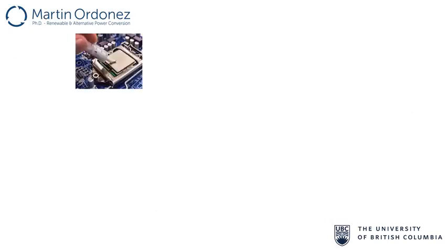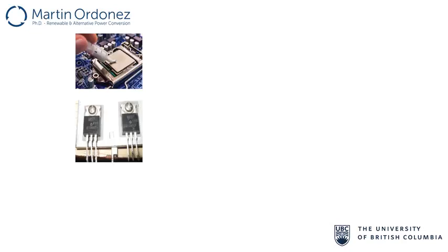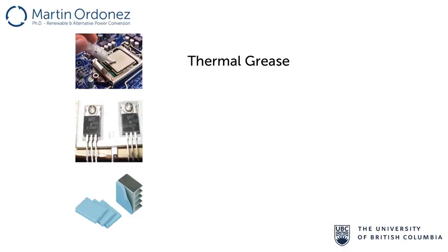As mentioned before, in order to have a proper connection between the MOSFET and heatsink, a proper thermal conductor should be used. The thermal conductor can provide a good thermal contact between the MOSFET and heatsink to make sure that all the area of the MOSFET is properly connected to the heatsink, and also ensure that the MOSFET is electrically isolated from the heatsink.